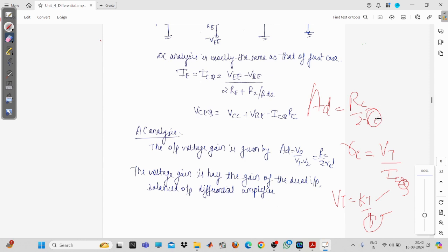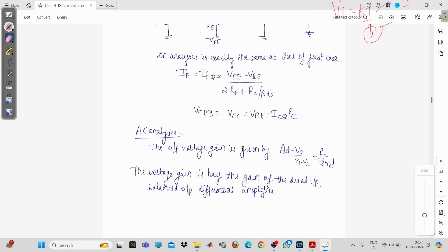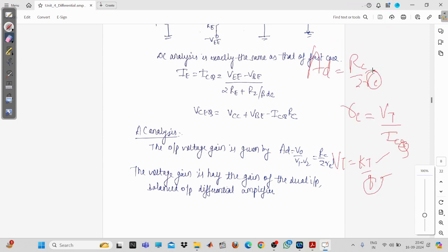If you keep your differential amplifier at some other temperature, your voltage gain will vary. So voltage gain depends upon the temperature, and this is not acceptable for our differential amplifier, or for our operational amplifier. So we need to make our differential amplifier independent of this variation. You can see RE will vary because of the temperature. So in the next class we'll be studying about the swamping resistor, which will eliminate the temperature variation, or which will eliminate the RE parameter variation.